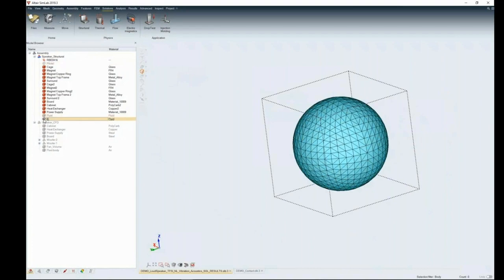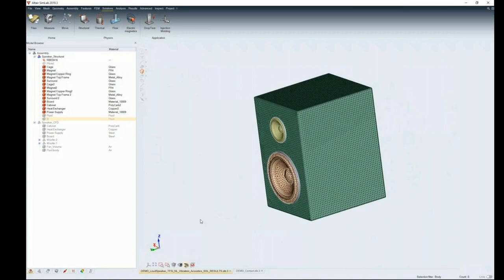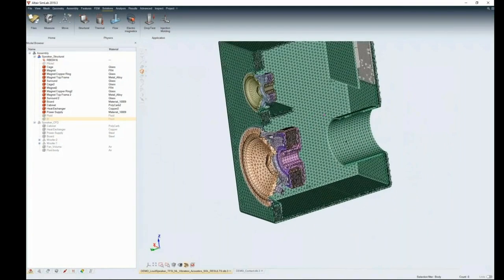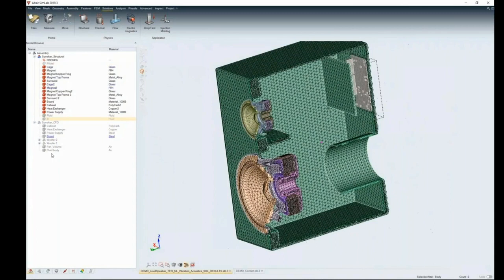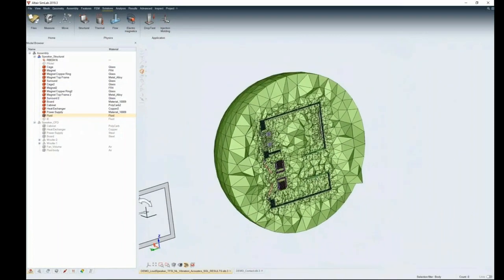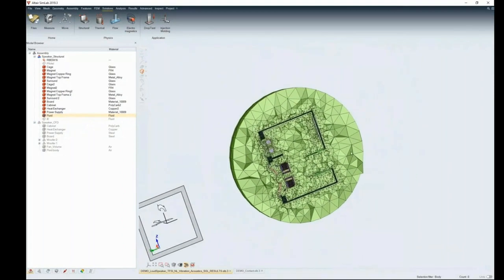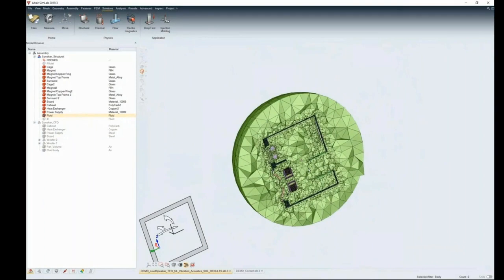Now in the structure part, you have another fluid domain. In the structure part, irrespective of the structural parts you have, make sure that you have a certain number of layers across the thickness. You also need the fluid so that you can do a certain acoustic analysis. I think that's the beauty in SimLab in the model management. It can have various meshes exist, connecting or disconnecting depending upon the kind of simulations you're doing, and it will allow the user to play around and make sure you submit certain jobs and the coupling happens pretty much between both of them. Now what you see here is the acoustic mesh, and you see again the cabinet, and these are the number of layers.